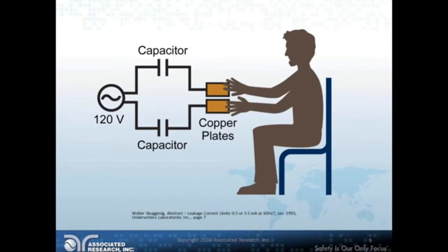Now, on average, the human body has about 1,000 to 1,500 ohms resistance to the flow of electrical current. I will say that that is a conservative estimate. When I say conservative, I'm kind of saying worst case, because that becomes a pretty large contact area. That is basically me grabbing a metal conductor with each hand, about the size of a Coke can, so complete contact with the hand.